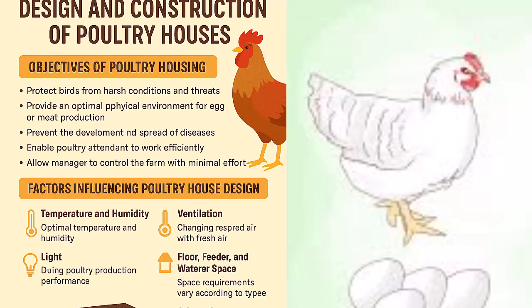Construction details: the foundation and the recommended features and functions. Foundation: concrete or permanent base. Function: stability and support. Floor: raised 30 centimeters above ground to prevent water seepage.